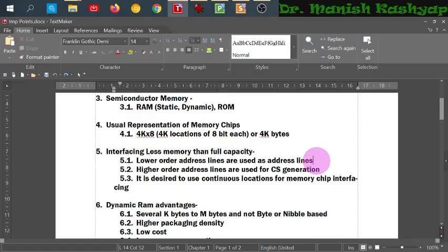And if you want to use full capacity of the address bus, then you will have complete 1 megabyte memory. But if you have any less memory, then it is preferred that you should begin from the starting addresses, means 00000, then 00001, 00002, and so on, right? So it is preferred that you begin from the numerical order of memory only. You should interface your memory in that order. Or if you interface it from some other location, it should be in continuous fashion.